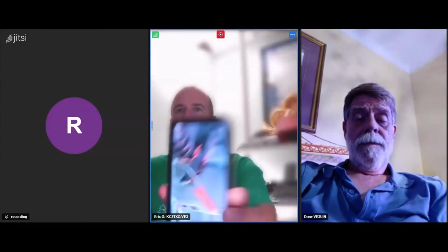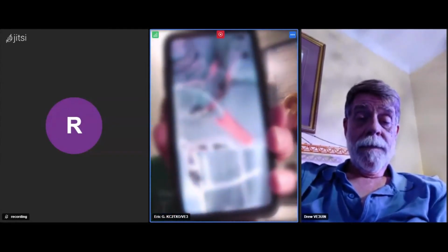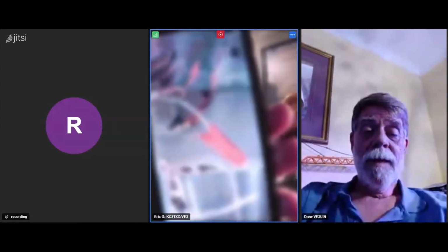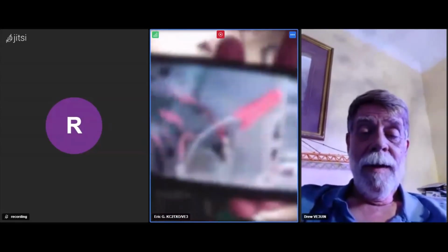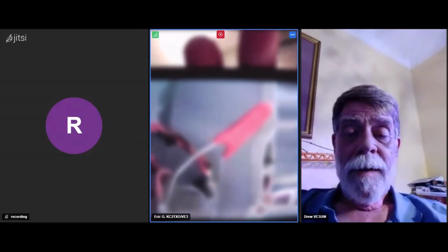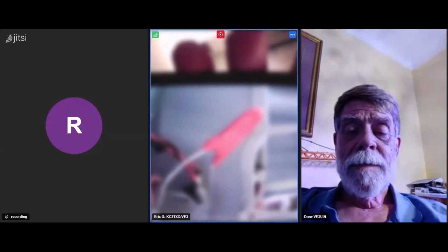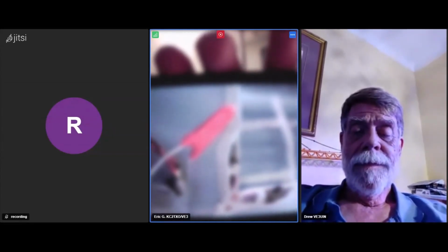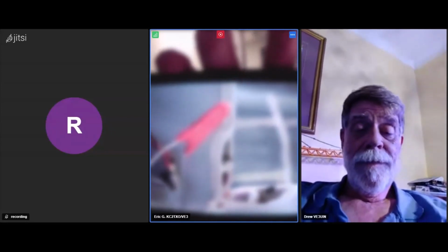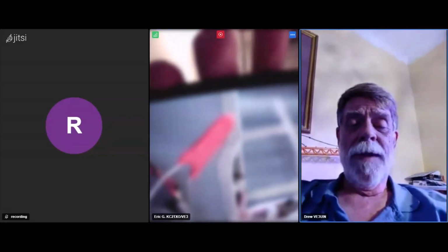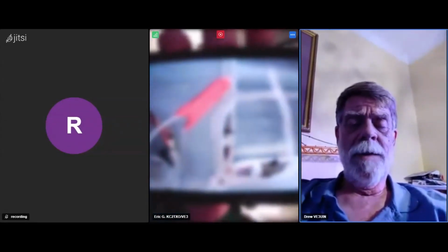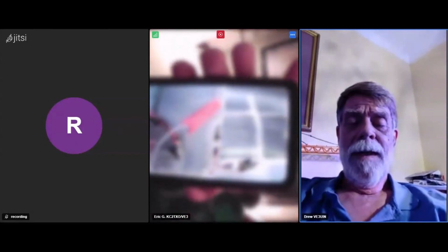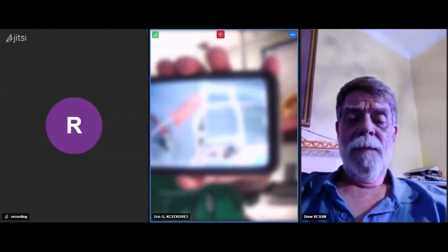But actually, I did take a picture of the inside of the box of my end-fed antenna. And that's the capacitor there. It's fuzzy, but I guess the only way to really check that is to take it out of circuit and put it on an LC meter. Yeah, you can put it on an L meter, but it should be 100 picofarad marked on it. Oh, yeah. I don't know off the top.